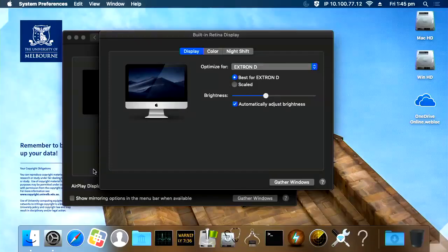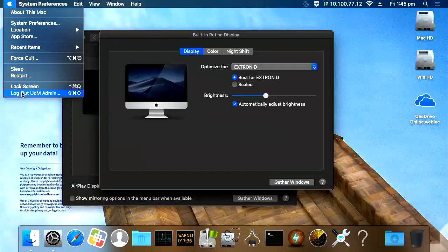This device actually generates a little bit of noise, and your noise at the output is the sum of the noise at the input multiplied by the gain of this device, plus whatever noise this device produces, and that's your total noise power.